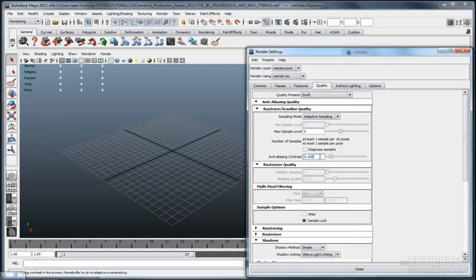For example, if you reduce the value from 0.1 to 0.05, which means you reduce it by half, the final quality of the image will be much sharper. The quality is increased very much, but sadly the render time will increase as well. So it's a matter of finding the correct trade-off between quality and time. Just remember that the more you decrease this value, the more the quality and the render time increase.